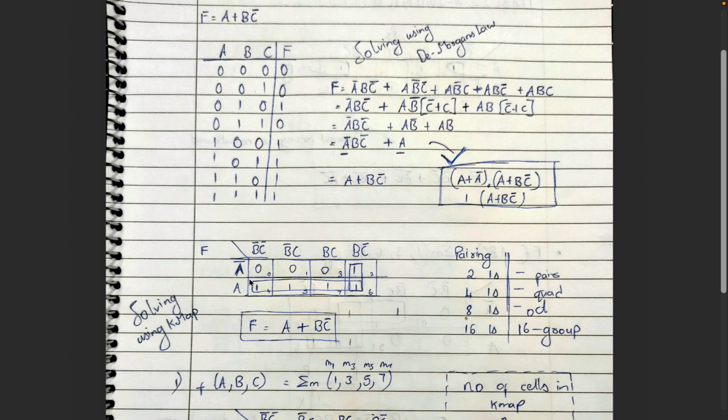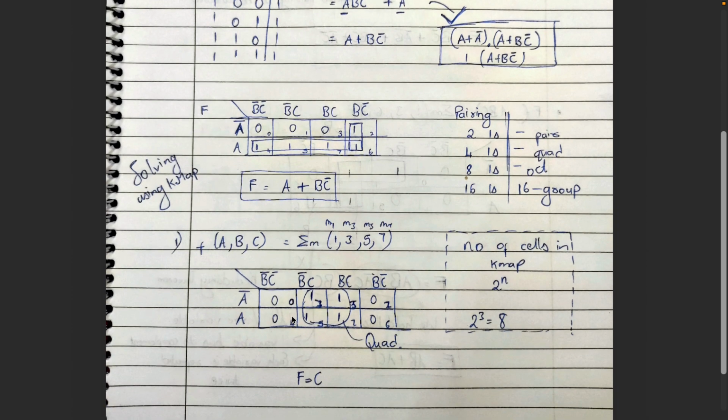Now I write it down. Now you can see that when I take this term, all the things will get negated or added up. So we are left with only a. Here what happens is we have a plus a bar, bc bar. So a plus a bar will become 1. You will be left with bc bar. So that is how you will get your final expression.